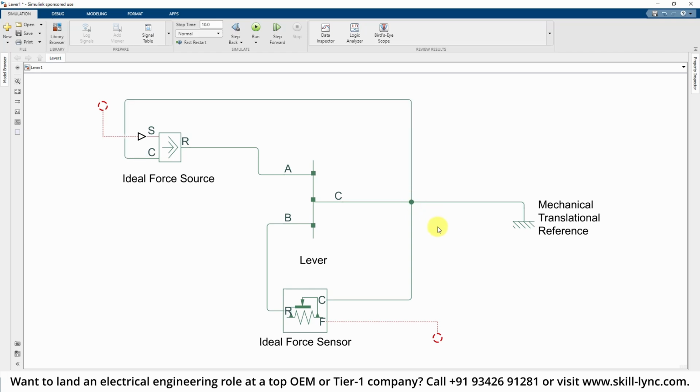Or where it appears automatically that where you want to connect. Now if you are making some wrong connection, let's say for example you are connecting this F block over here, right? Or you are trying to connect this F block over here, which may not be right. So let's see what happens, right? So your connections will appear always in red, right? So when your connections are firm, then only they will appear as perfect as green dot, right? So F is the output of the sensor, which we cannot connect to the reference, or it's not going to be a green signal. Its signal type is going to be different.